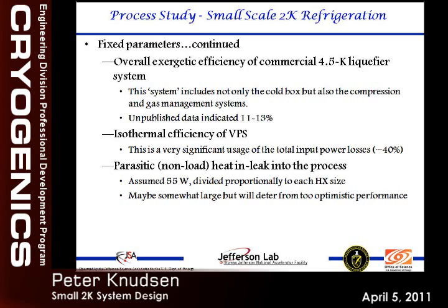The other fixed parameter is the overall exergetic efficiency of the commercial 4K liquefier. That system, as I mentioned, includes both the cold box and the compressor system, so it's kind of a package deal. If you went out to a commercial supplier and said, I want a 4K liquefier, it would be the whole thing: the cold box and the compressor system.